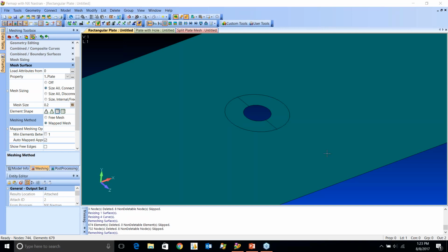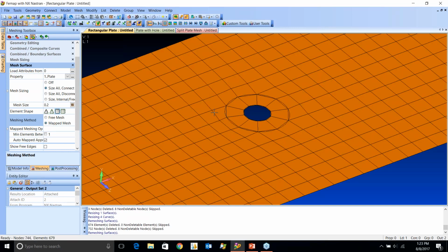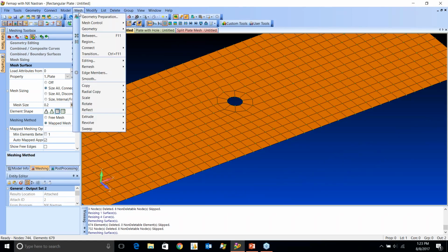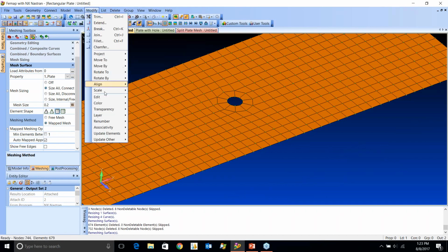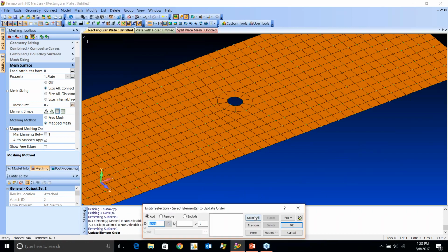Here's a good one. How can you transition from linear elements to parabolic elements? That's a little tricky because the idea of a parabolic element, as I mentioned, is that it assumes a form of a solution using a second order function, whereas the linear uses a first order function. So going in between those, it takes just a different element type. Using this mesh size that I have here, we'll just make these parabolic elements again.